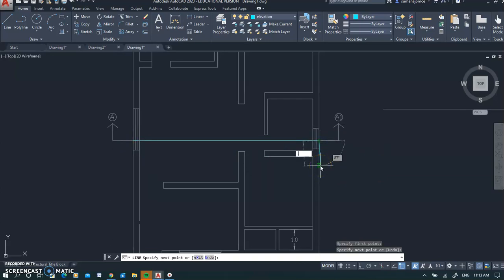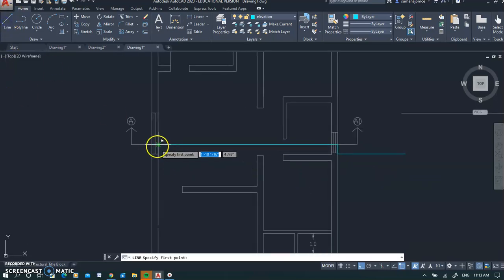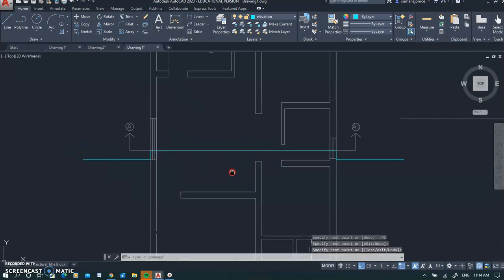And we go down by 0.45. We know that the plinth height is 0.45, but you must remember that I am not in ortho. Be careful. Go to F8 for ortho, go down by 0.45 and continue the section line. The same thing happens on the other side. From here, the building goes down by 0.45 and that's the ground line. This is the section line, okay?